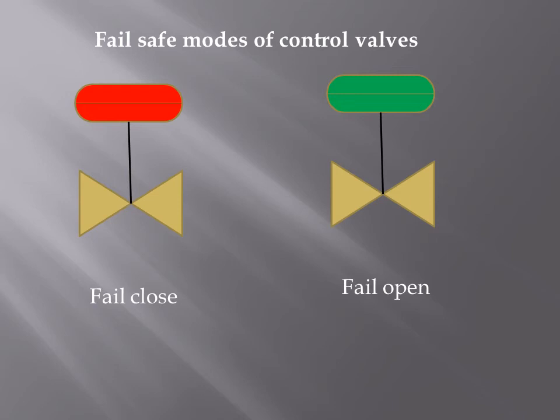Normally, red colored valves are failure-close valves in the firing circuits, because anything which adds energy or heat to the system should go closed on instrument air failure. This is just to bring the system back to a safe condition. On the contrary, any valves which remove heat or pressure from the system, like the reflux and vent valves, are all colored green. They open on failure.